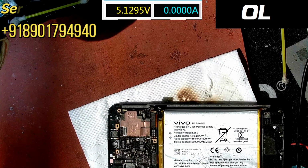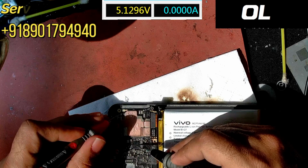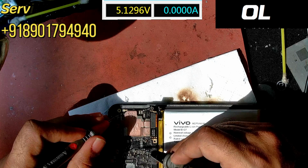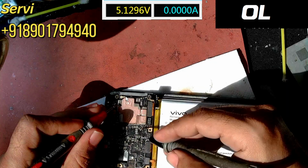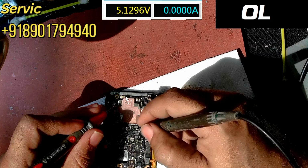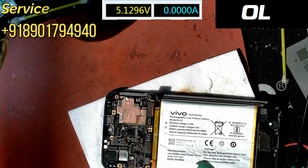Now we check the VPH, the V system line, and see what the diode value is. This is the power IC and the buck inductor. In between there are some capacitors, 7 to 8 capacitors connected to the VPH line. So we check the VPH lines. Let's check it. 363, it's okay.